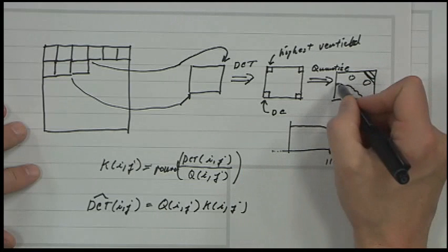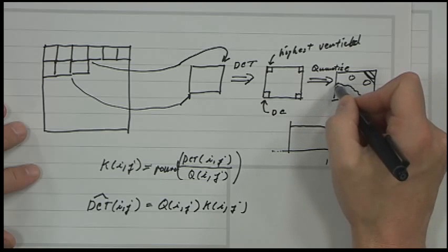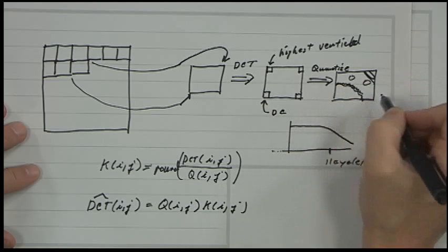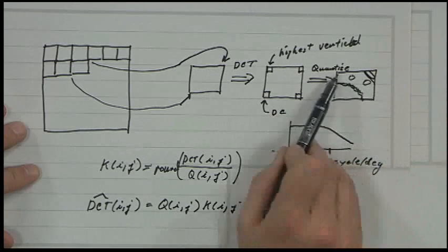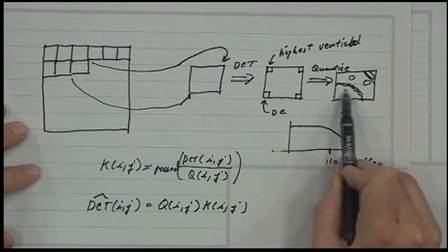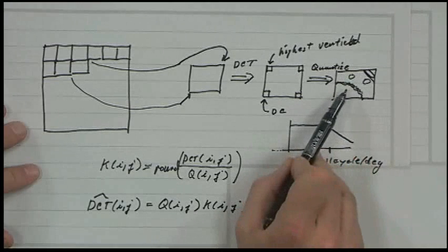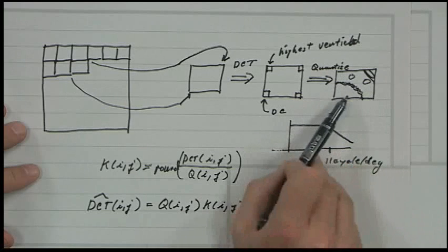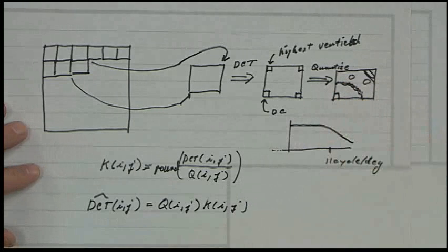The reason you use a zigzag is because the boundary of constant frequency is sort of like a circle here. So if you did it like this, you would stop getting runs when you hit this region here, right? You tend to do better if you do the run length coding this way, which is how the standard's specified. So you do run length coding this way, and now the DC coefficient you code separately.